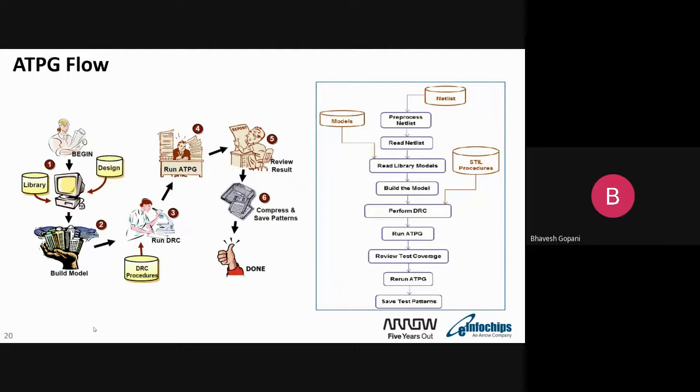This is a very important stage in DFT, because here, when everything is ready, the pattern generation needs to start. It always starts with the ATPG flow: my design has MBIST insertion ready, scan insertion ready, and all the required outputs ready, and now I need to start ATPG. Certain things need to be done before starting; we can't directly start with pattern generation.